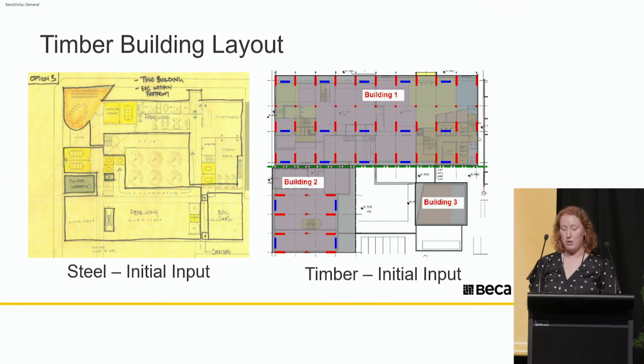Making timber projects work, and thus timber connections, is primarily about getting the building approach that suits timber. At concept stage, we have an opportunity to influence this and get the design team on board. With steel, we like to funnel the entire building's loads through specifically designed connections into a discrete lateral load system. Timber really doesn't play nice with this concentration of load. With timber, we need to operate on smaller and more consistent grids with lower loads transferred through each connection.